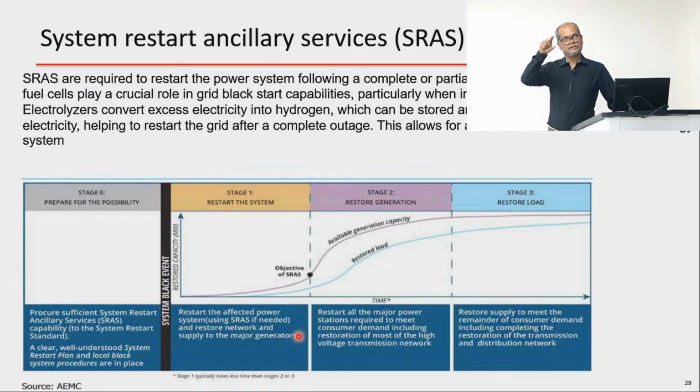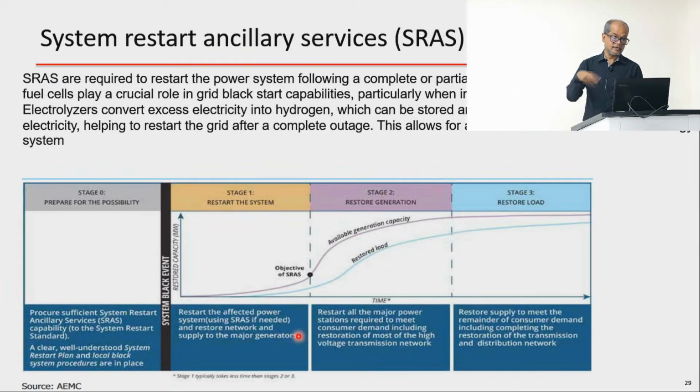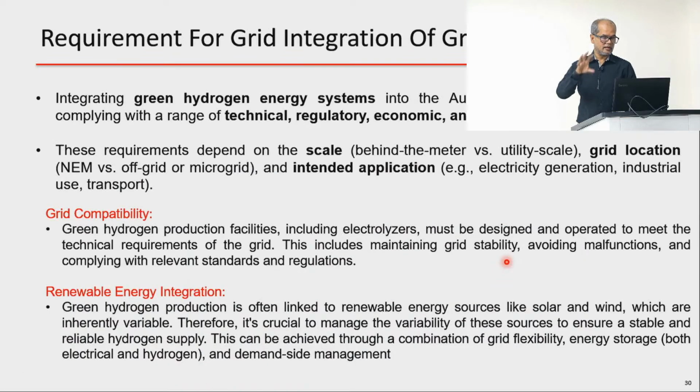Sometimes if you have a synchronous generator that is separately excited, you have to excite the system first as well. And then, as I say, they restore the load, bring the available generation, and finally bring all the remaining customer, transmission line, and distribution line online. So this is in brief, but definitely when they plan, they have an established plan that they actually follow to do that.